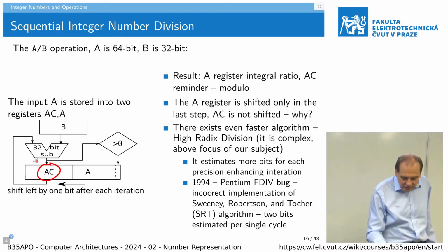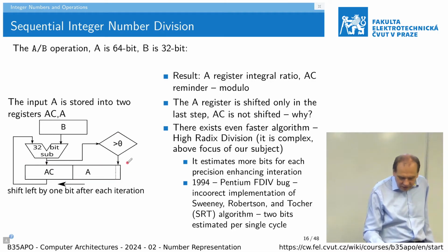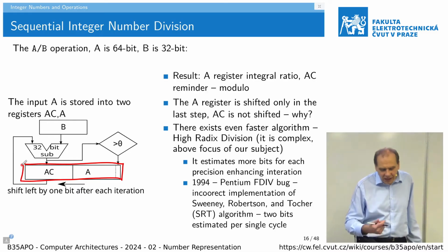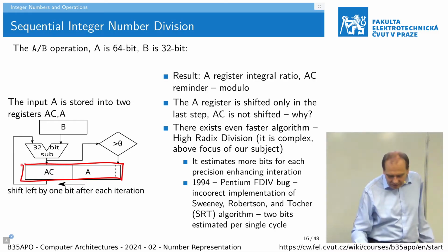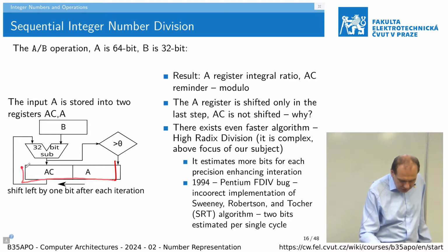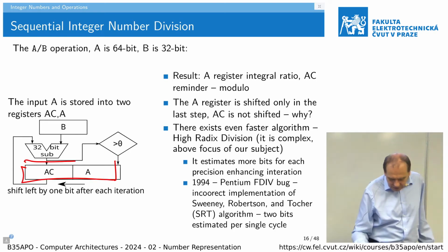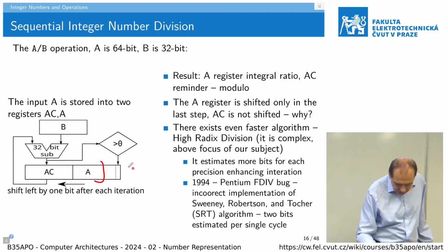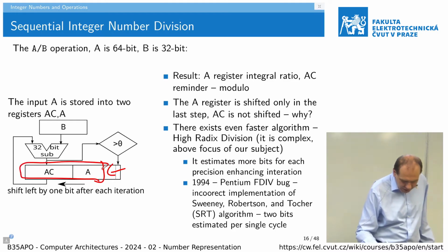And if we reuse this register even to store the result, then it has the advantage because we know that a remainder is 32-bit, but the input value is 64-bit. And we know that each time when we compute one digit, the maximum remaining value is 1 bit less. So basically, there is a shift in the result, and this is still a remainder, and so on.